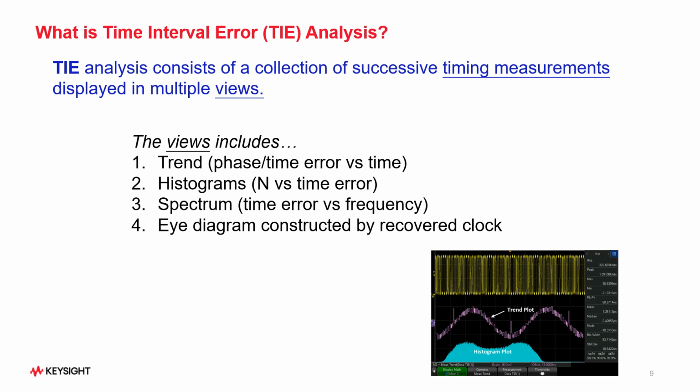What is real-time jitter analysis? The various types of timing measurements can be viewed in different formats. The most common view for repetitive jitter measurements has traditionally been the eye diagram, where the scope is triggered with a real hardware clock and the NRZ data is captured repetitively with an infinite persistence display mode to visually show the worst case timing and voltage variations. An eye mask opening can then be applied to this type of display to test for compliance to a specific specification.